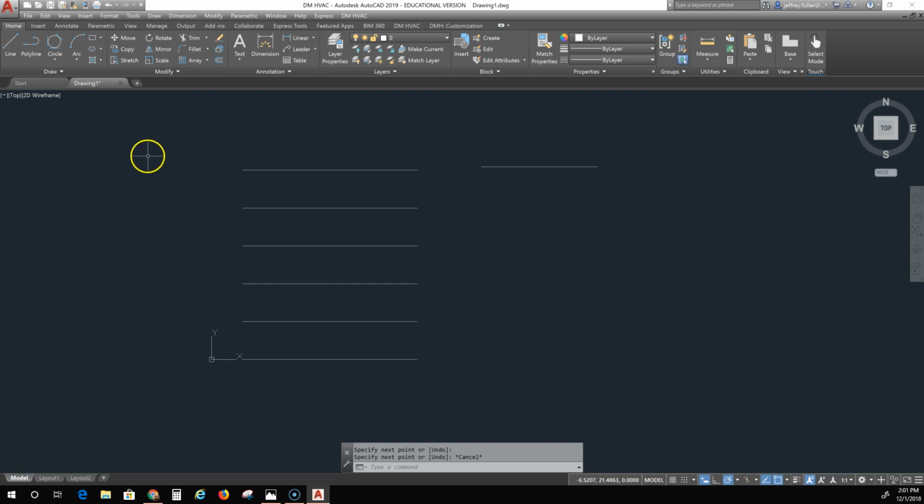and then I escaped from the command, and I used the offset symbol right here, the offset tool, and I type in the distance I want offset. Right now it just remembers what I had in there last time. So you can type in 4 or 5 or whatever it is you want, hit the enter button, select the object, and click again to place the object.